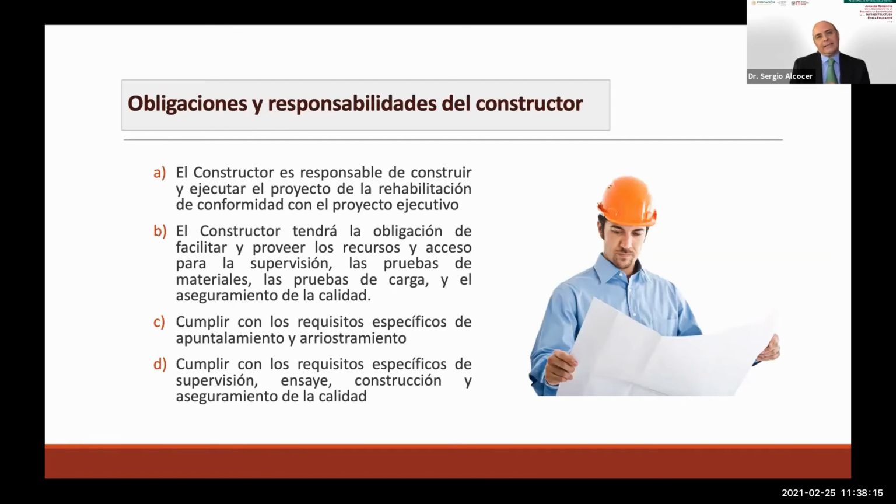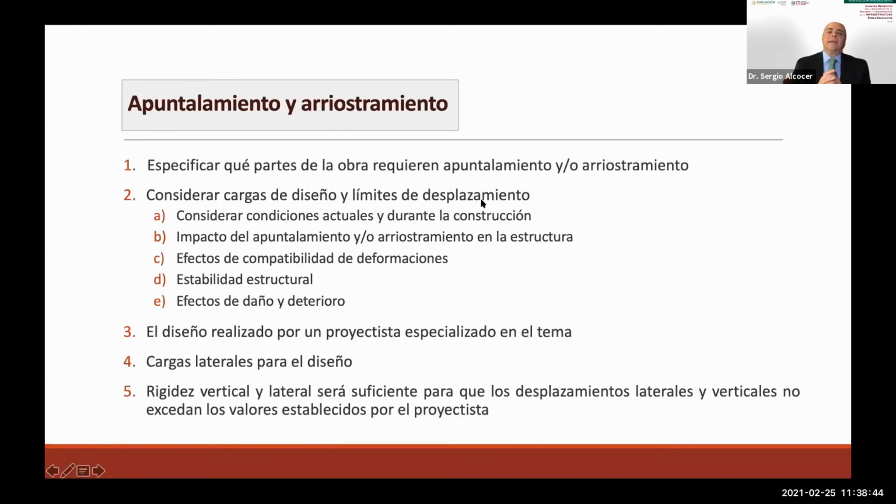Number one. Number two, we need to use rods or steel bars that also comply with the Mexican applicable standards. If not, the epoxy will fail, the reinforced concrete will fail, and eventually the joint will fail between the new structure and the old structure. That's why we emphasize the technical guide to comply with these standardization processes.